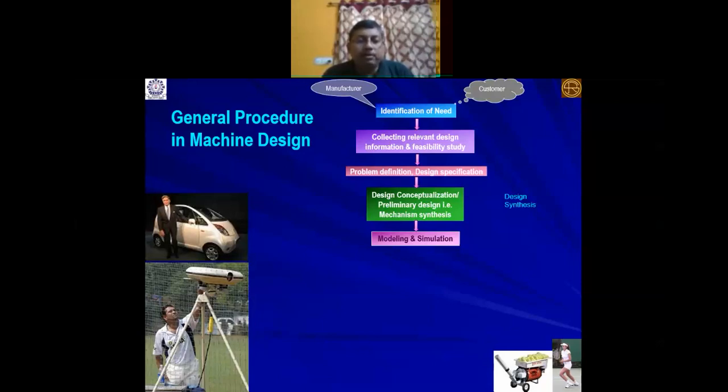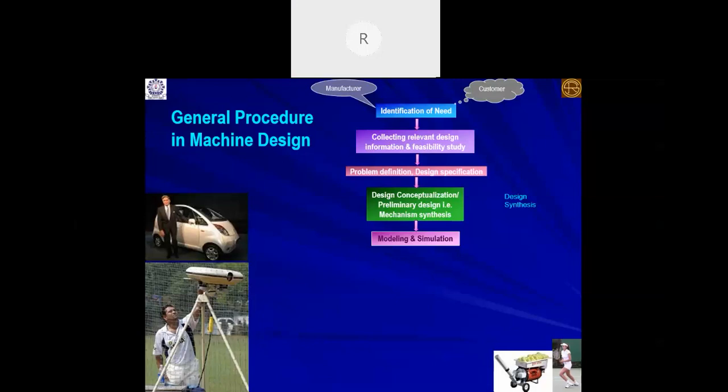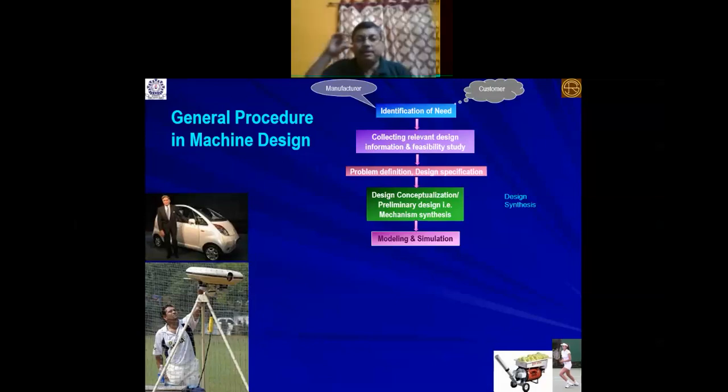Now, in order to find out the torque, you need alpha. Now, what is alpha? Alpha is the time derivative of your angular velocity. That means RPM. That means you have to solve not only the RPM, you have to solve the equation of the acceleration. That means full kinematics you have to solve. Once you solve this one, along with your mass property and inertia property, you can solve the kinetic problem and you find out the torque.